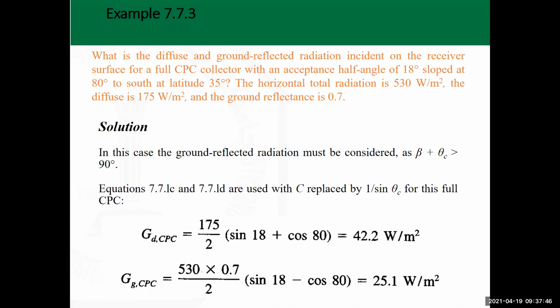solar fraction, and then screenshots that show the calculations being done for different numbers of collectors and the corresponding value of the solar fraction. You may take it one more step by making a plot that you collect from these screenshots. For example, for a certain number n of collectors, say 15, you get a solar fraction of 60%. If you made them 25, you get a solar fraction of 72%.